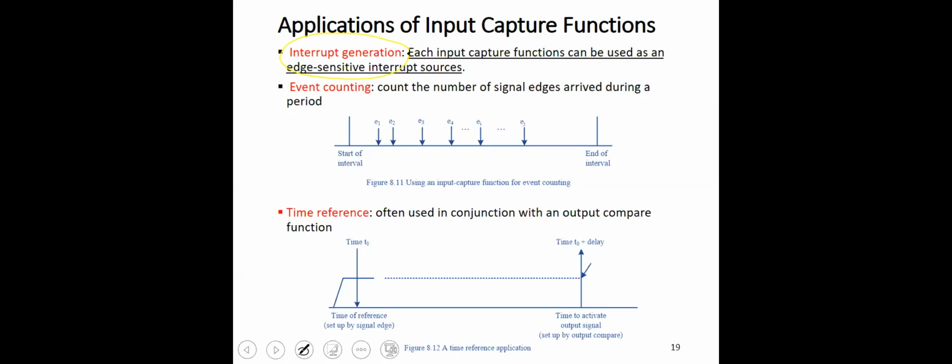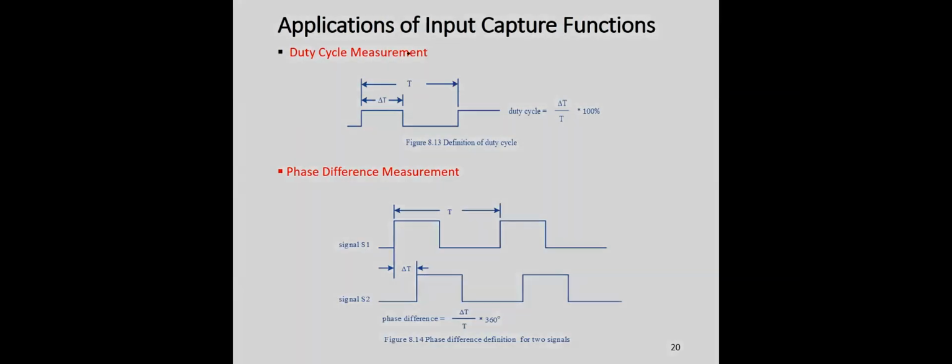So this adds to the capabilities of the microcontroller in terms of the ability to interrupt it based on some external events. In this case, we have 8 events that we can monitor in addition to the IRQ and the XIRQ that we already discussed in chapter 6.